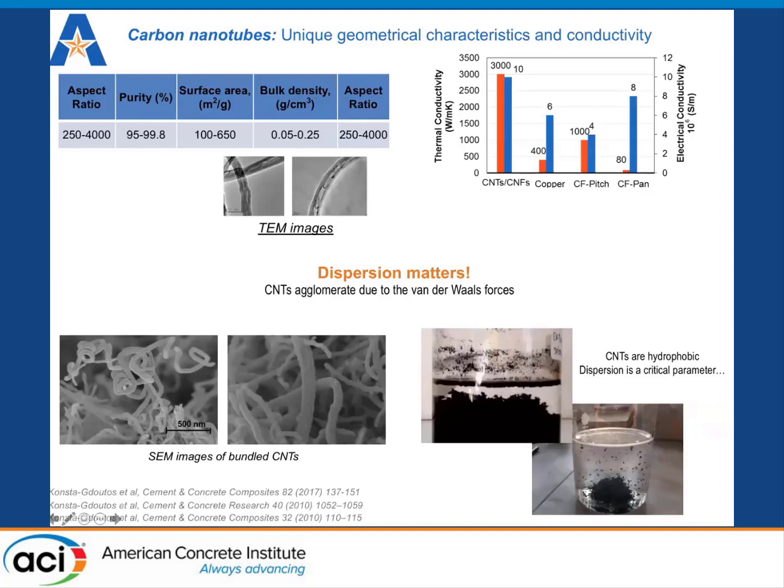Carbon nanotubes, we all know, exhibit remarkable intrinsic properties, including strength, stiffness, and electrical conductivity. It was long shown that, depending on their geometrical characteristics, aspect ratio, and morphology, low carbon nanotube concentration levels in cementitious materials allow electrical conductivity and impart enhanced mechanical and durability properties, also, as an added bonus, sensing ability.